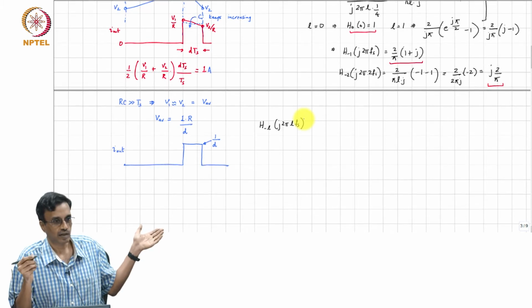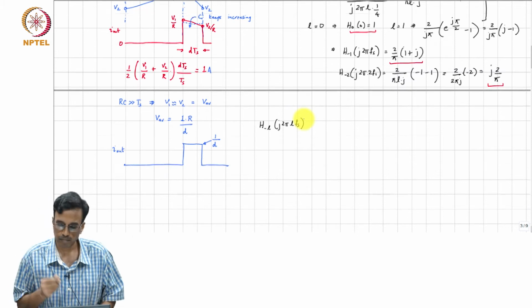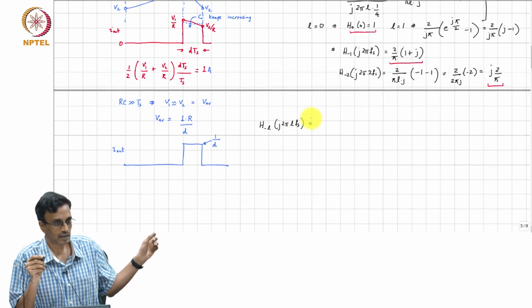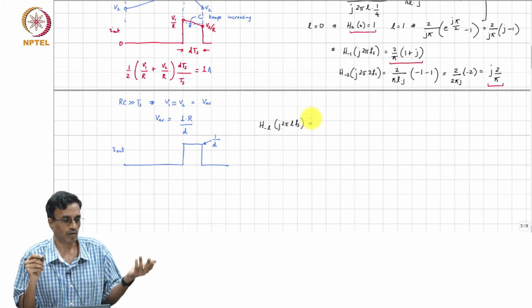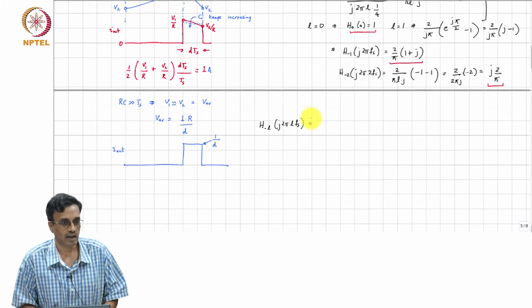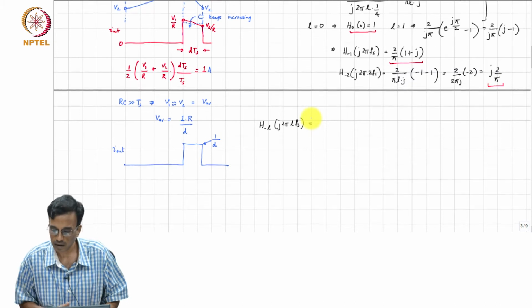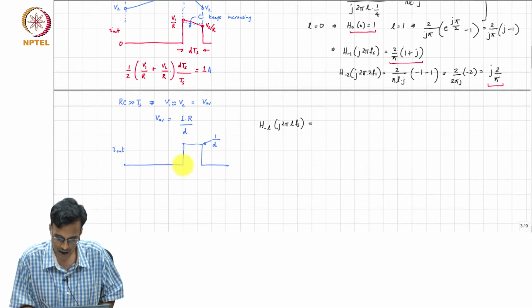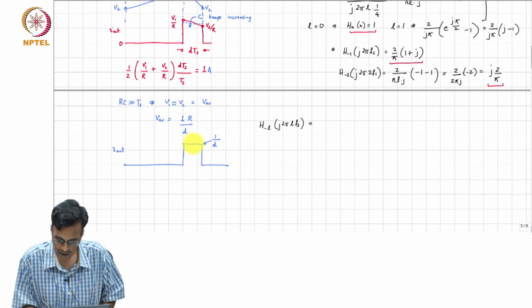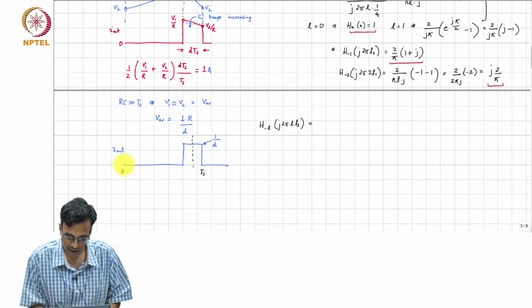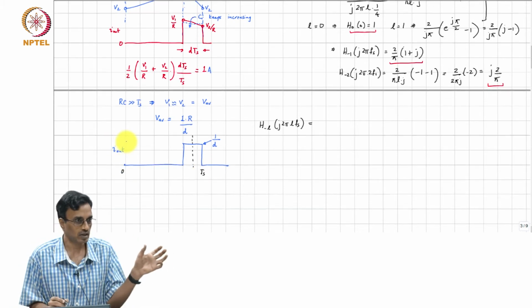We just have to find the Fourier series of this waveform, right. And how do you find the Fourier series? We know the Fourier transform of a rectangular pulse. We just sample the Fourier transform at L times Fs, correct. So, you can think of this as a rectangular pulse with a delay, where this is 0 and this is Ts. There is another pulse just before 0, because it is a periodic waveform.